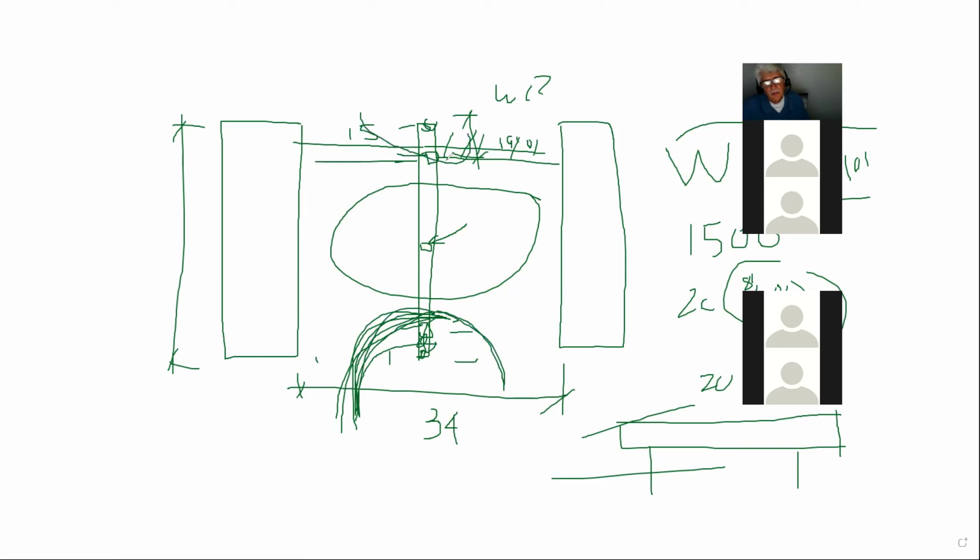Yeah. So I call this a non-circulating area. And I said, put your columns there and there. So right away, we were able to save. And then what I did for him is, of course, I did the whole analysis, snow load, 50%, 100%. I did 6 load cases, and then of course with my spreadsheet, I was able to just throw it into the spreadsheet, and it gave me the size of the beam, you understand? And ended up saving him about $1,000 just on steel.